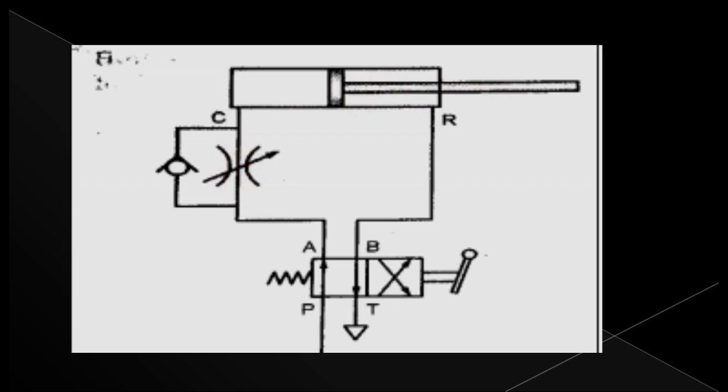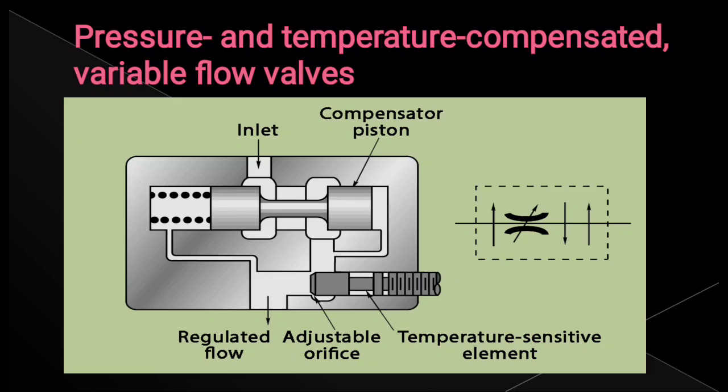If the opening is higher, the piston moves faster. If the liquid is coming back, this is actually a single direction flow control valve, so it will not allow flow in this direction. It will allow the liquid, open the check valve, and by that the liquid is transmitted to the direction controller. So like that the flow controller is used in a system.